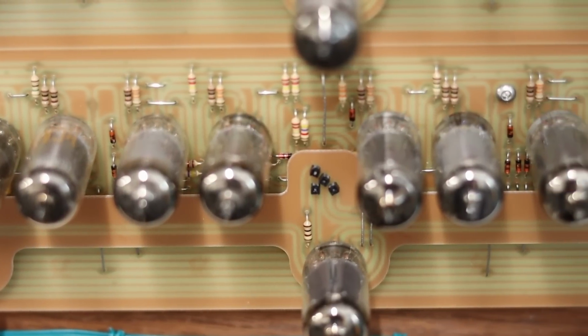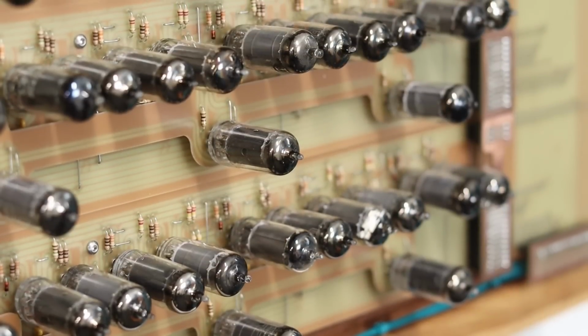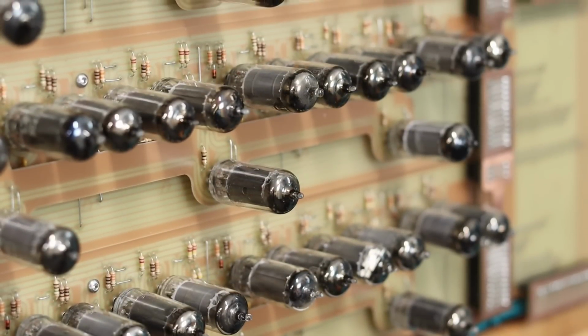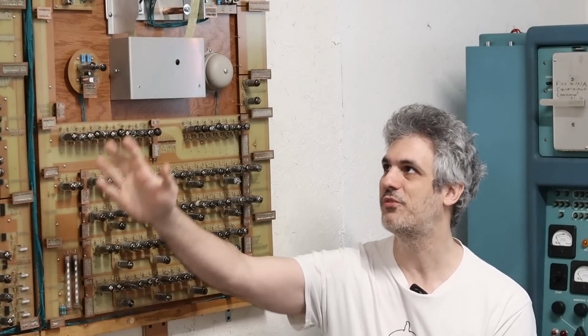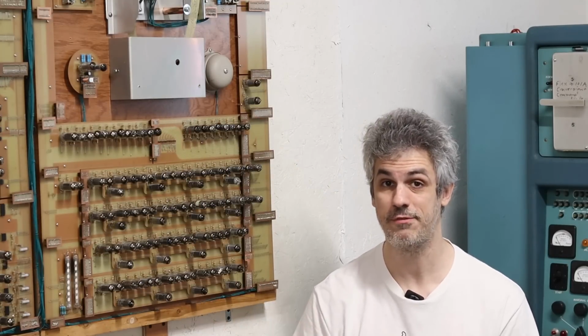I also had to remove and change quite a lot of resistors because I used some very weird resistor values to try to get that 6AU6 VFD combo to work, but I've gone back to just the exact same resistor values that I use for every flip-flop everywhere else on this board. So this should effectively work, I hope. I haven't actually put any power into it yet, so I have no idea if it's going to go up in smoke or if it'll just start functioning.